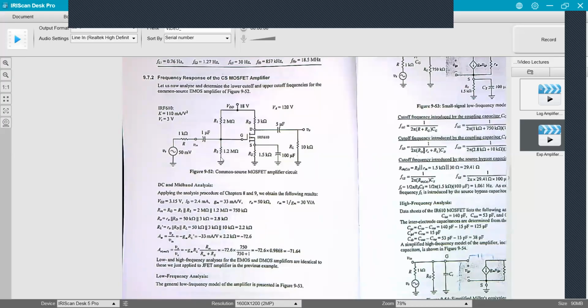So basically for heat reasons, and also it makes it easier for it to flow in the other parts because it's going to be like plus 3 volts at that point, right? Well, not so much easier to flow in the other part. You don't want to pull any extra current off of your supply voltage for no good reason. What if instead of running this off of a supply voltage of 18 volts, it was a battery? The smaller I make these, the more current flows out of this battery, the quicker the battery dies. So if I'm designing this thing to be out in the field somewhere, not connected to a power supply, just running off of batteries, I would want those resistors to be larger because they'll draw the least amount of current from my battery, so it could last longer.